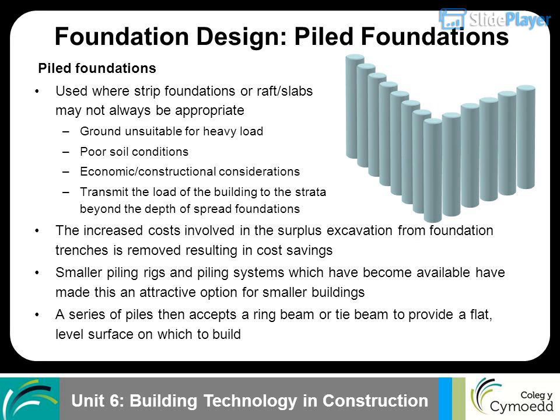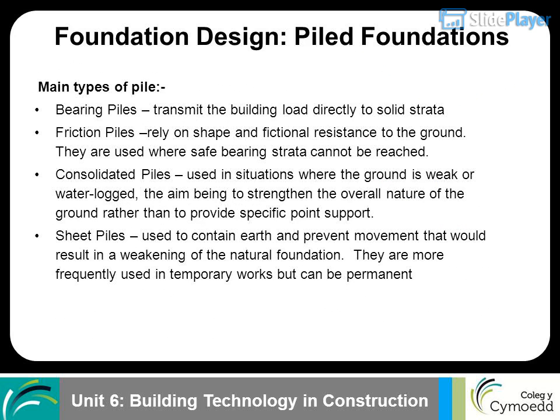The increased costs involved in the surplus excavation from foundation trenches are removed, resulting in cost savings. Smaller piling rigs and piling systems which have become available have made this an attractive option for smaller buildings. A series of piles then accepts a ring beam or tie beam to provide a flat, level surface on which to build. Foundation design: piled foundations.